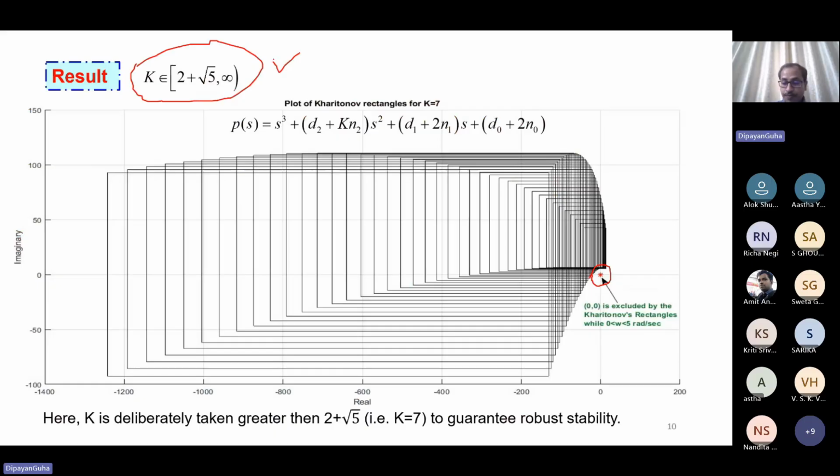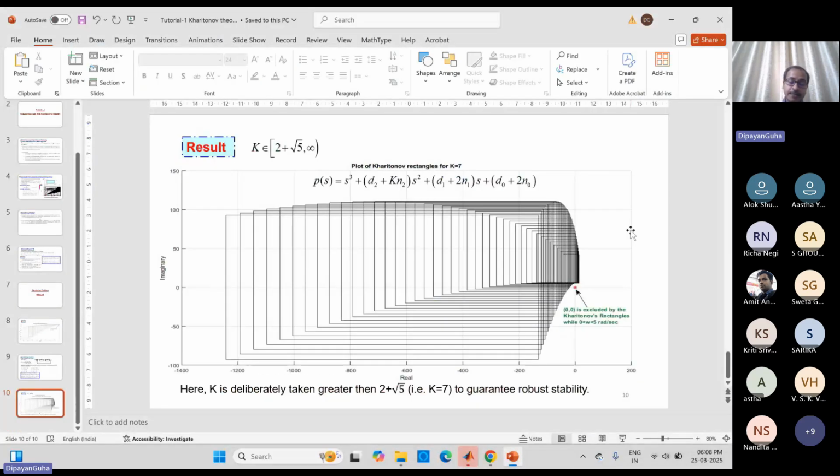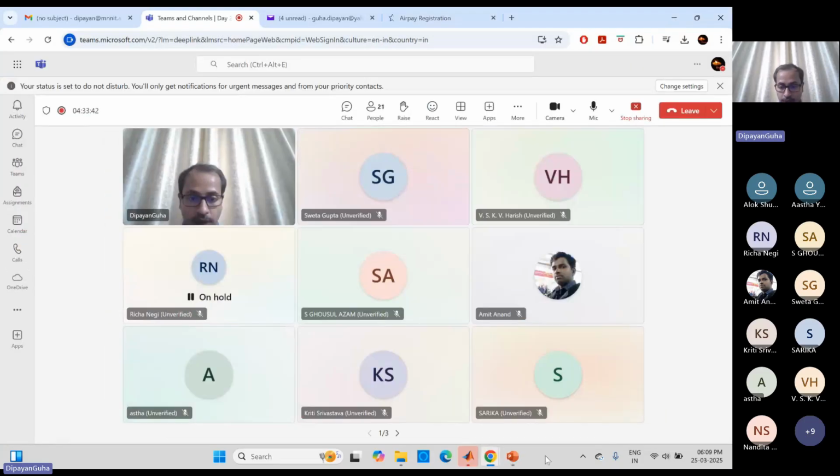So this is a very simple test through which the robustness of LTI systems can be demonstrated. However, in real-time practice, we are actually dealing with nonlinear systems. For those nonlinear systems, this type of algorithm is not applicable. So if I want to achieve good robustness, then I have to consider some advanced robust control algorithm, maybe the sliding mode approach, or H infinity control, or a mu synthesis like algorithm, for ensuring robustness of the developed closed loop control framework. So I can show you the simulation results.